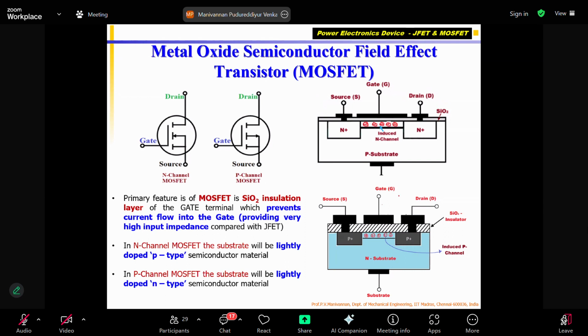When I give a negative voltage like this, this should be connected to this, and between this and this, I connect my load. This is plus minus. This is VDS, correct? And this is my load resistor. Plus is connected to the source, and the minus of the VDS is connected to the ground. We call it a ground terminal for the P channel MOSFET.